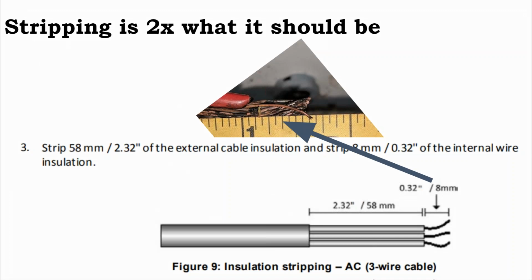And that arc fault was caused by stripping too much cable off of the conductor and it arcing because it's right next to this other conductor. So, poor workmanship. And I'd say that is what most problems are on a solar array, is poor workmanship. So take that in mind when you're selecting an installation contractor or considering doing it yourself. These manufacturers specify exactly how much, and it can be a different amount at different terminal ports on the inverter. So that's all stuff that you find in the installation manual, but you have to follow it, or at least make sure that whoever's stripping the cables is looking up the terminal lengths and getting them right.